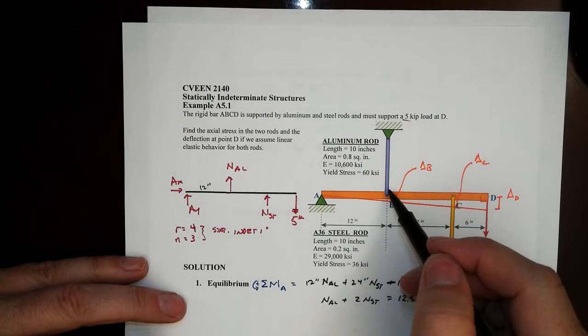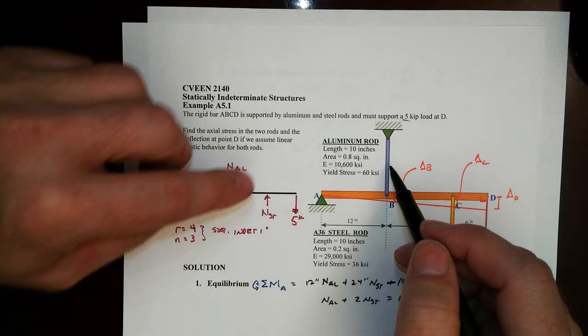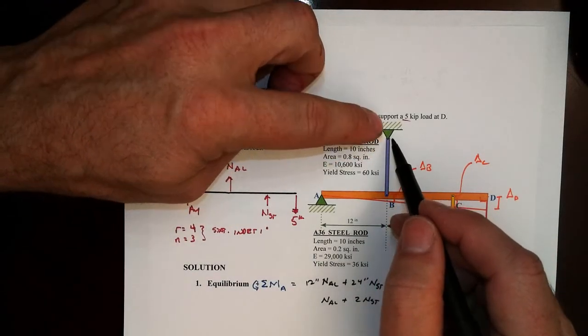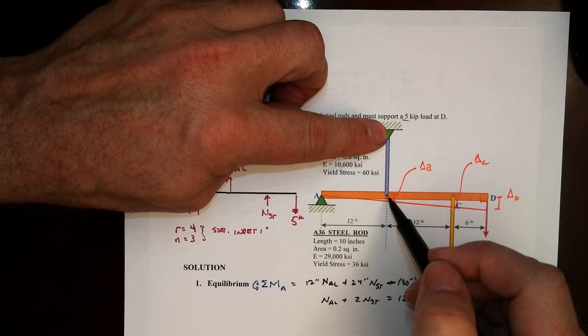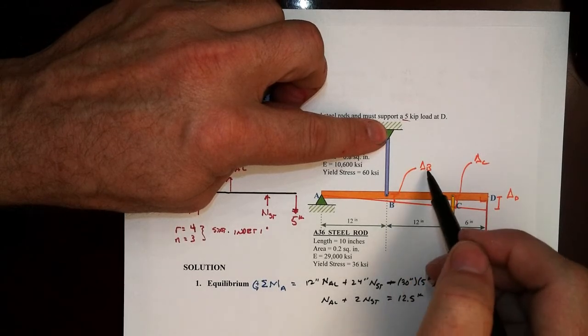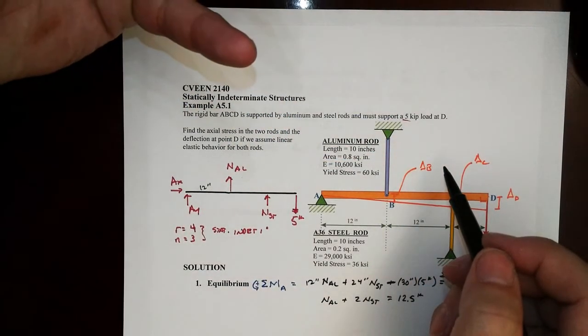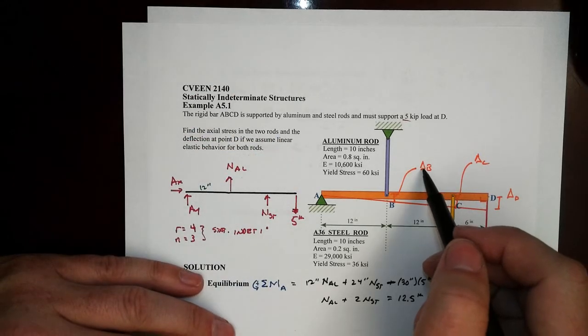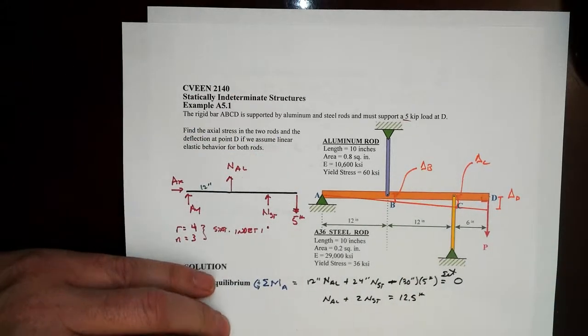Now, one of the reasons why that might change is if there's a gap here before that ends up connecting and elongating something, or if the top of the rod were to displace also, maybe by the same amount as delta B, then that would be a zero deformation. So you have to be careful about the linkage between a global displacement and what happens inside the member.